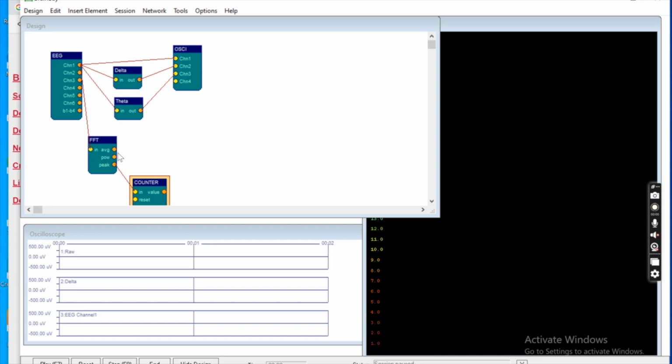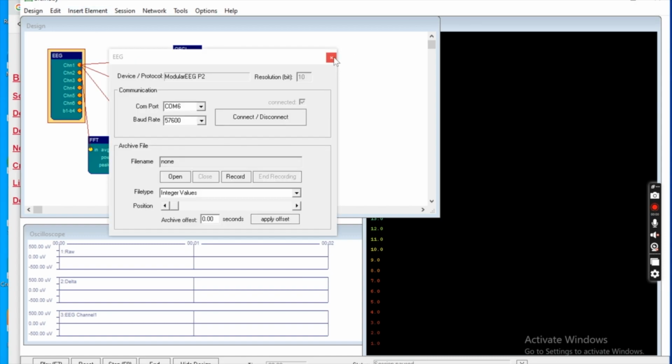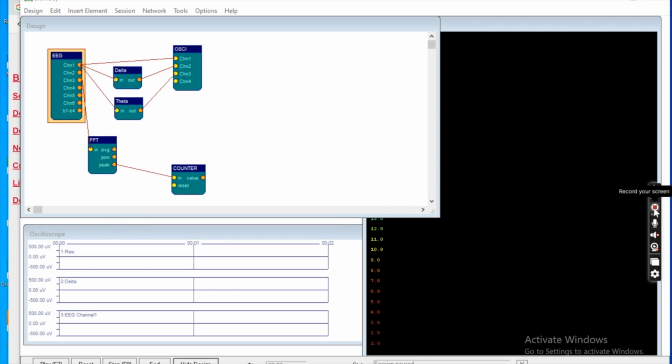So as the signal's coming in over the session, you can track the amplitude in the different wave bands, which has some use for tracking your own meditation and even just different states of mind, etc. So that's the basics there, really. We'll try and just get a signal now on our EXG pill, so we'll make sure that that's connected there, and I'll quickly hook up the electrodes, and then we'll see if we can get a signal reading and try and tune these outputs.